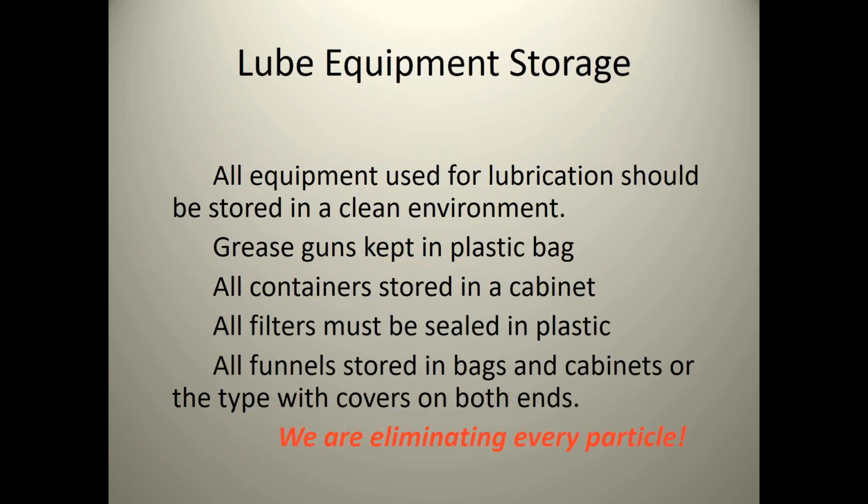Your lube equipment storage, where you're getting particles from: how are you storing your equipment? Keep your grease guns in a plastic bag. Keep all your containers in a cabinet if you're using oil-safe containers or other containers for moving your oils around. All your filters should be sealed. All your funnels should be in plastic bags. You can buy Ziploc bags from McMaster-Carr in any size you want. But keep those filters in a bag and keep your lube equipment in a bag. You're trying to eliminate every particle.